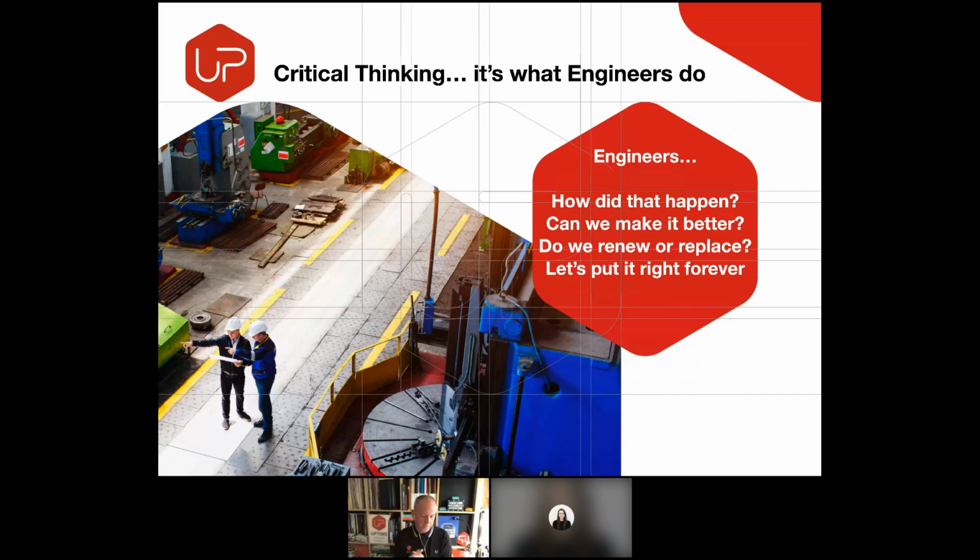So the benefits part of it, for me, all of the criticality studies I've taken part in over the last 15 years, all of it has been paid for, top line, by the reduction in the spares inventory and the removal, or not putting it in the first place, of planned maintenance that adds no value whatsoever. So from an RCM point of view, we look at the components and you have to say, what does this planned maintenance do for our asset and for the risks and consequences of eventual failure?